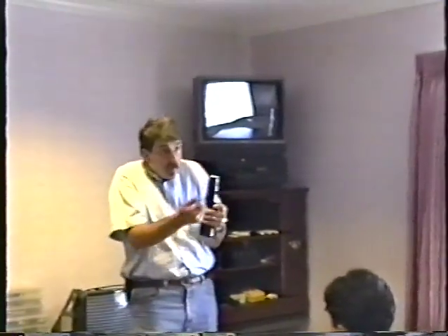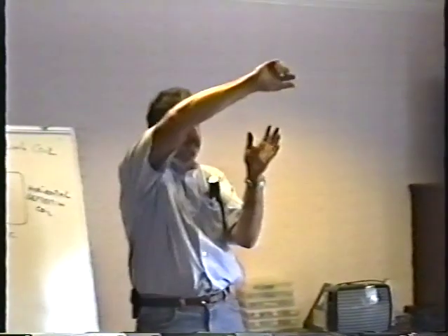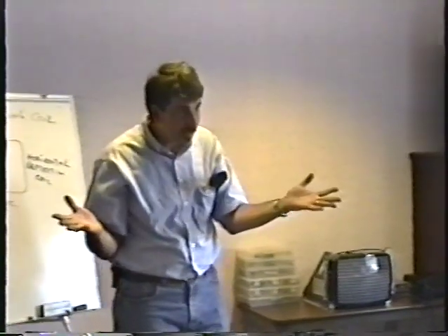The point I'm making here is keep your dang fingers off those rings. Don't just mess with the rings. Don't go, hey, what do these do? And start messing around with them, because what you'll do is you'll separate the red, green, and blue. Maybe you've seen this before on your home TV or on a video game. You see something with a blue halo on one side, or red or green. That's when the images, the red, green, and blue, are not all superimposed properly, when the monitor is out of convergence, as they call it.